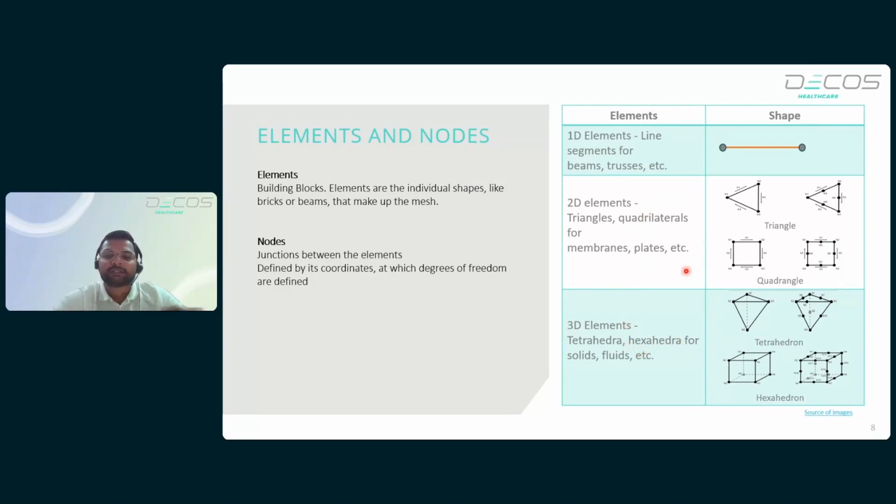Now, triangular elements are simple and versatile for complex geometries. Okay. And they are often used for fluids and irregular surfaces or solids. But quadrilateral and hexahedron elements are used for regular geometries like cubes, cuboids, and others. Okay, so the triangles or tetrahedrons are used for irregular or complex geometries, while quadrilateral or hexahedron elements are used for regular geometries. The accuracy will be higher with a quad or hex mesh, because you create more points to solve the problem. Okay, let's move to the next slide.